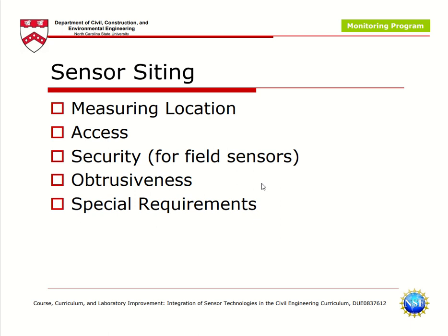Then the second important point about the setting of the sensor would be access. Your sensor should be accessible. For example, if I'm installing a sensor in a vehicle, let's say a car, inside the bonnet, remember the car bonnet has so many things around it, and sometimes it gets too less spacious, or too complex to identify the sensor that we have placed earlier.